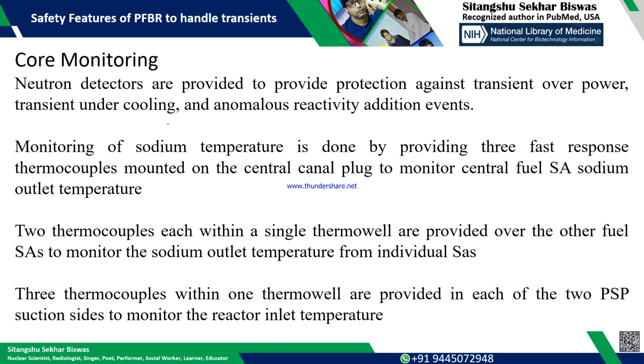Now coming to the core monitoring, it is a very important parameter to control the reactor. The neutron detectors are provided for protection against a transient overpower. In case of any abnormality, it will detect, and the control system will respond accordingly.